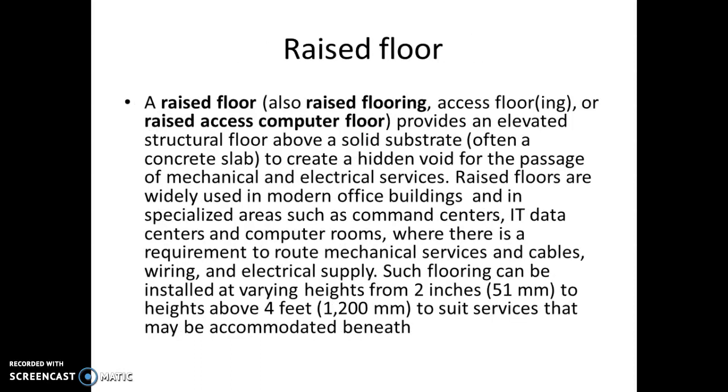The second method we come across is the raised floor. It provides an elevated structural floor above a solid surface. It creates a hidden void or a passage for mechanical and electrical services. This method can be implemented in many different office buildings where the cables, wiring and electrical supplies are mounted under one particular floor. We can raise the floor up to 4 feet.